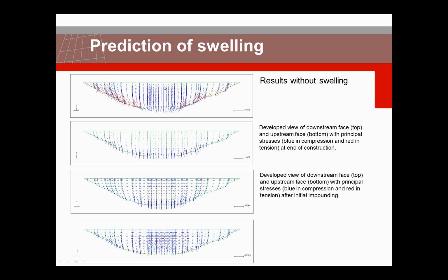And you see here that all the stresses are in vertical direction, because in the circumferential direction there are these joints which prevent circumferential stresses from being built up. And you also see that all the vertical stresses at the interaction with the foundation here, the blue here, are almost 0.